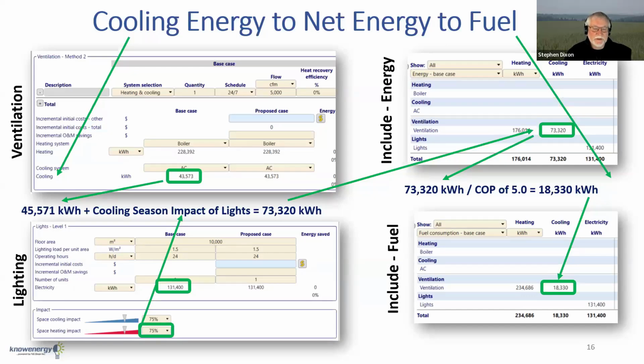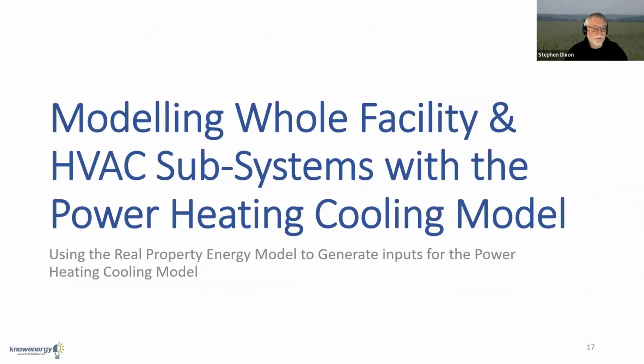If anybody has worked with building codes, sometimes when you're designing a building you're required to specify the TEDI, the thermal energy demand intensity of the building. And in fact, RETScreen can calculate that because TEDI is defined as the envelope requirements plus the ventilation requirements minus the internal heat gains divided by the floor area. Well, RETScreen has all those numbers. I was doing a workshop a little while ago with a company that does that kind of simulation and modeling work. They said, well, couldn't RETScreen do that? And in fact, I sent an email about the next version of RETScreen, because all the numbers were there, just a matter of displaying the result on the screen. So it seems like some of this stuff is superfluous, but it's quite useful when it comes to actually modeling these systems.